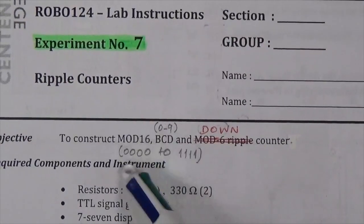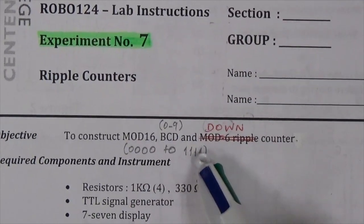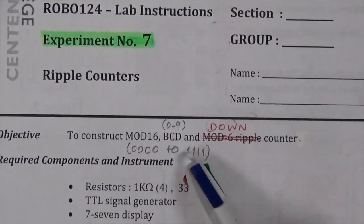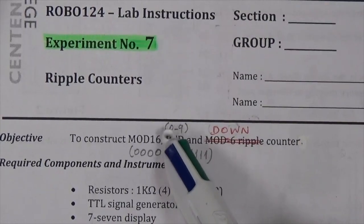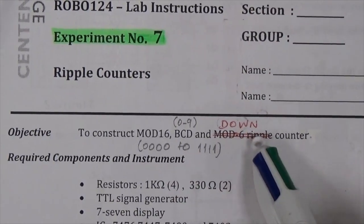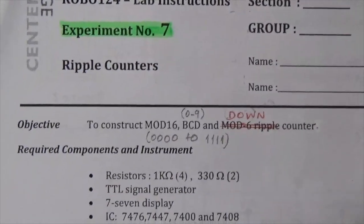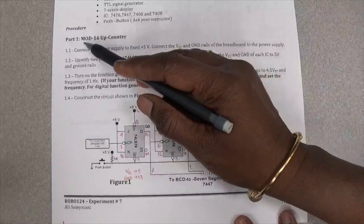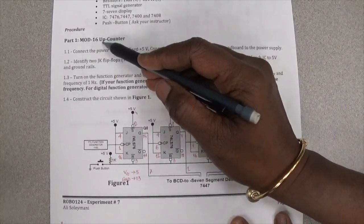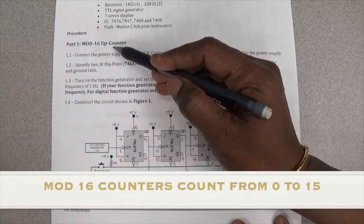So mod 16 counter is going to count from 0000 to 1111, which is 0 to 15. BCD counter is going to count from 0 to 9. Down counter is going to count from 7 to 4: 7, 6, 5, 4. First circuit that we are going to build is mod 16 up counter. Up means counting from 0 to 16.